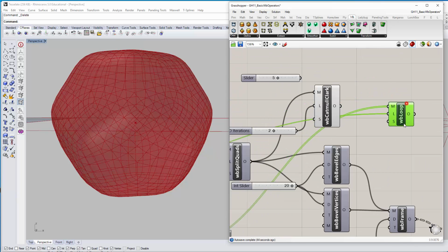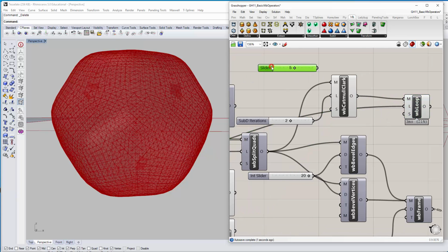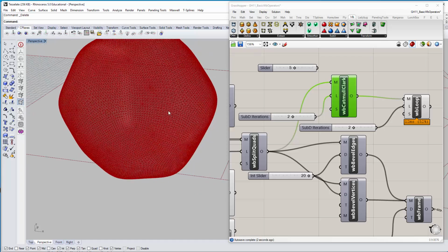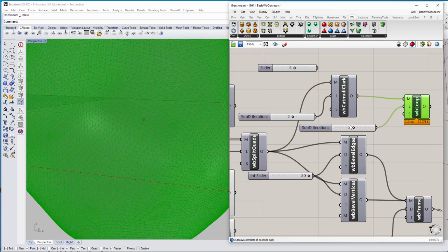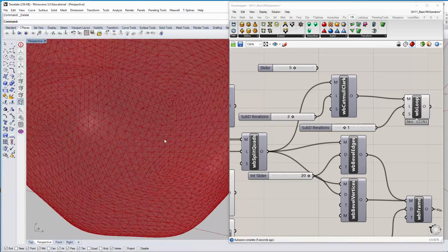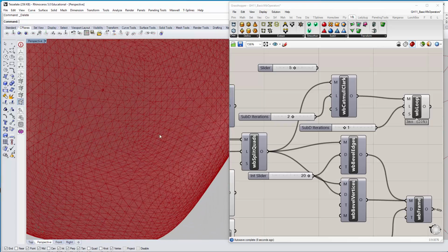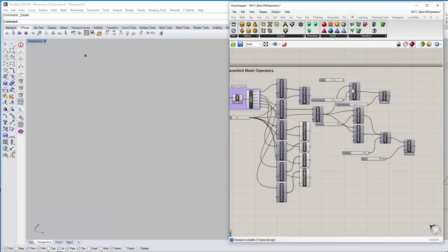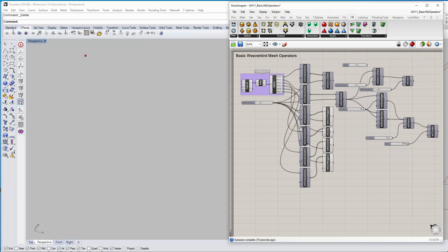after the Catmull Clark. So do this. I'm just copy pasting these so you can control them individually. It just depends on how dense or how detailed a mesh you want to end up with. And at this point, instead of being quads, now these are triangles. So this is how all of these things work. This is just a very quick example file to show you that these are all things you can mix and match to get a lot of different crazy configurations. Okay.